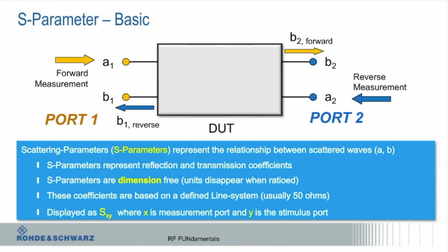The main thing that changes things more than anything is temperature, other than mucking with the connectors. If you loosen a connector or remove a cable, you definitely should always recalibrate.